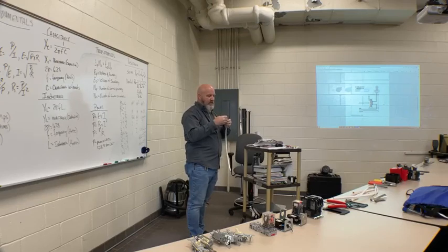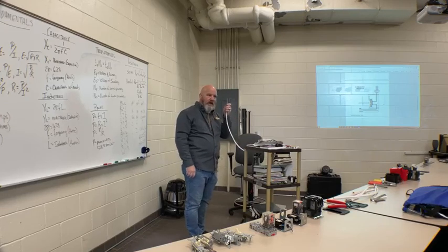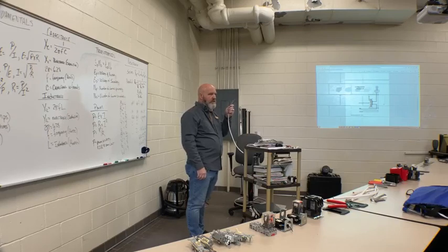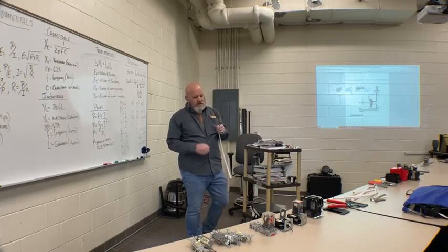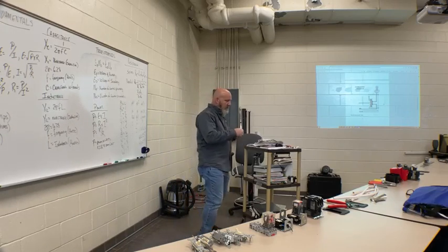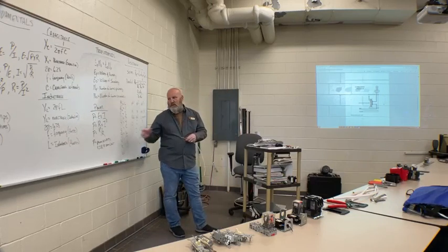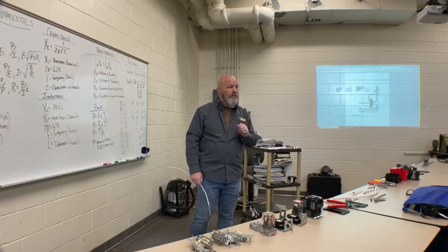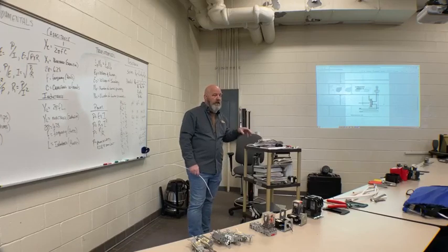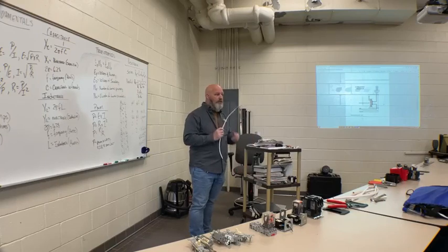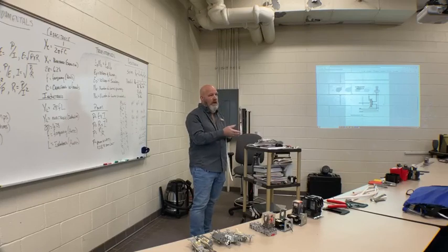They outlawed that in 2014 because homeowners see a white wire and they think neutral. So there were too many people doing their own work in 2014. Plus there are smart devices. Let me take that back. The industry said they did it because of smart devices. A smart device is when you use an app on your phone or something to control your lights. Well, smart devices need a neutral. They have to have their own power to run. So now, in 2014, the code said every switch box must have a neutral in it that is actually a neutral, so you can hook a smart device up later.